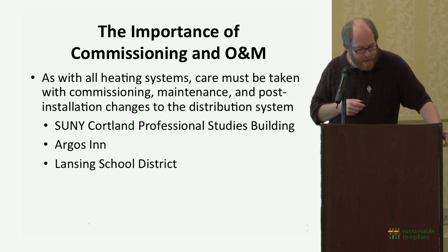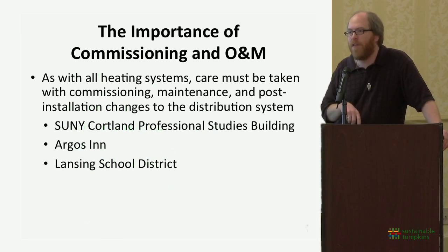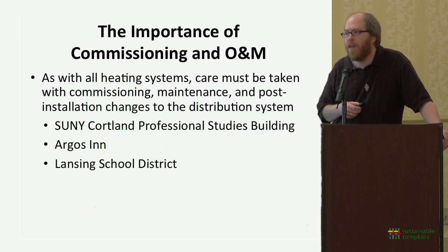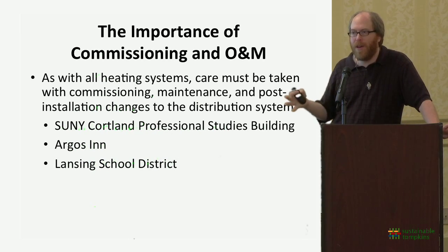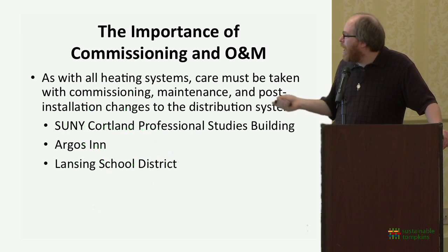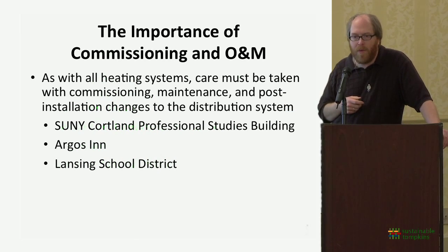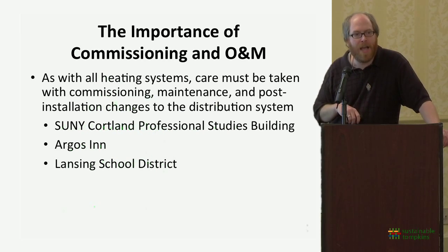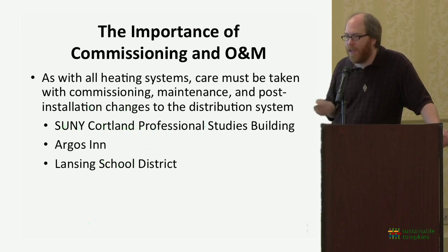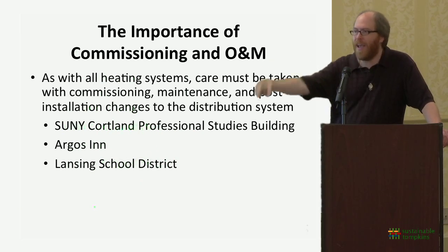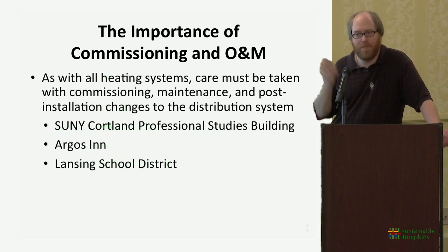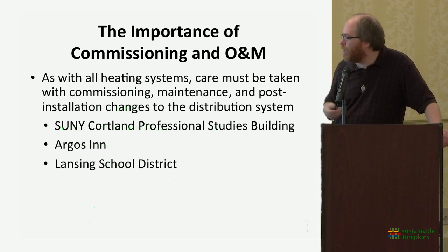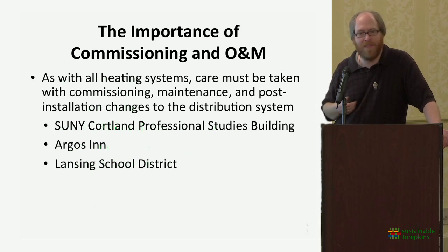Commissioning. It's very important that these systems, after they're constructed, actually be commissioned and monitored. So great care must be taken when you do this to make sure that you're actually going to get those efficiencies out of the system. The SUNY Cortland Professional Studies building, we found that for the first year didn't save us an awful lot of money. We had finally had the ability to hire an energy manager. One of the first things they did was look at this, and they discovered that our loop field hadn't been filled all the way. And so our loop field wasn't filled with glycol, and it wasn't pumping that heat out of the ground. Once that was repaired, it works much better.